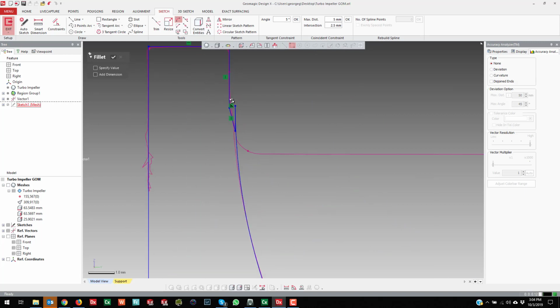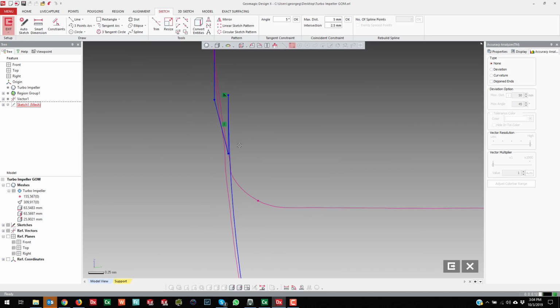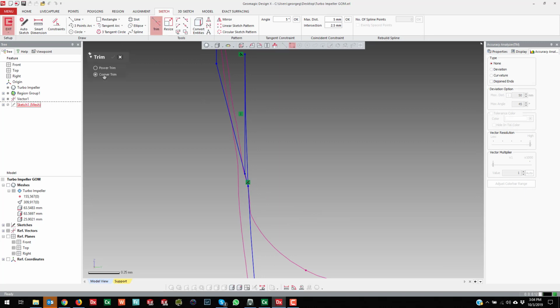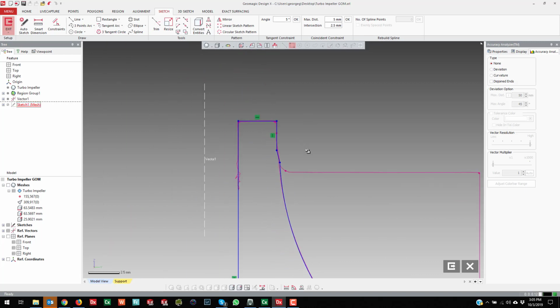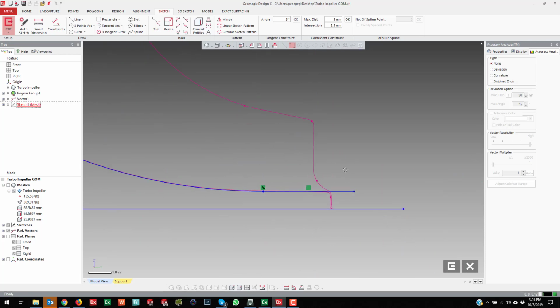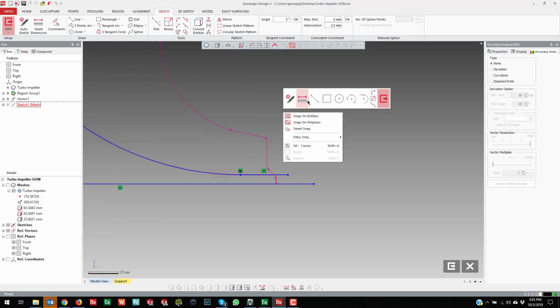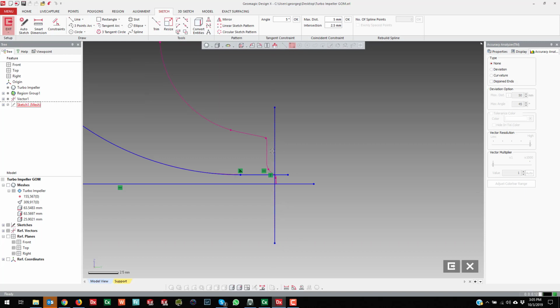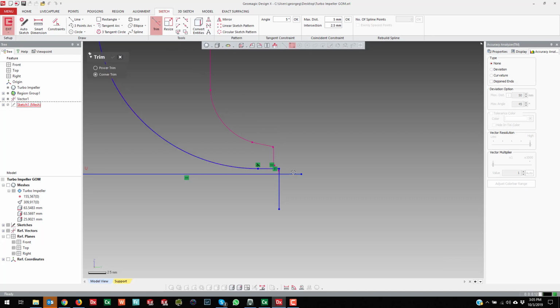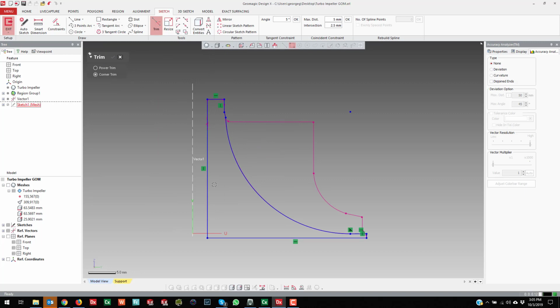And you see it went past over here. So what I can do is trim this stuff together. If I use the extend, I could say extend out there, then come over and do a corner trim from this to that, and then go ahead and delete this guy because of where that ended up was up there in space. And then this all looks pretty good over here, and I should have kept that vertical too, by the way. When I drew that initial rectangle, I should have kept the vertical, and I could have dragged it over here to do that. So corner trim there. So you see, this is what my goal is, to create that inner revolve profile.